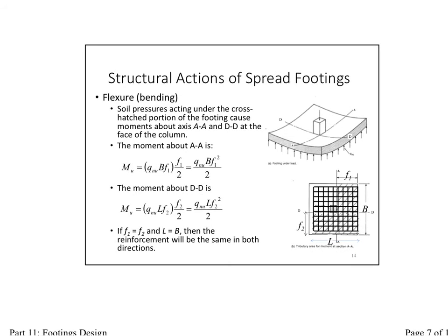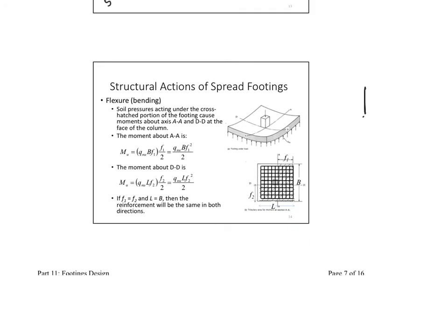Over here is the flexural. How do I calculate the flexural demand and capacity of my footing? Remember, the footing is a cantilever. So I simply need to look at this here. Here's my cantilever, right? And I need to know this load. Remember, where's the critical section? Probably here. And then where's the load? It's the load coming from this side, pushing up. I have to get this load to be able to calculate the moment.